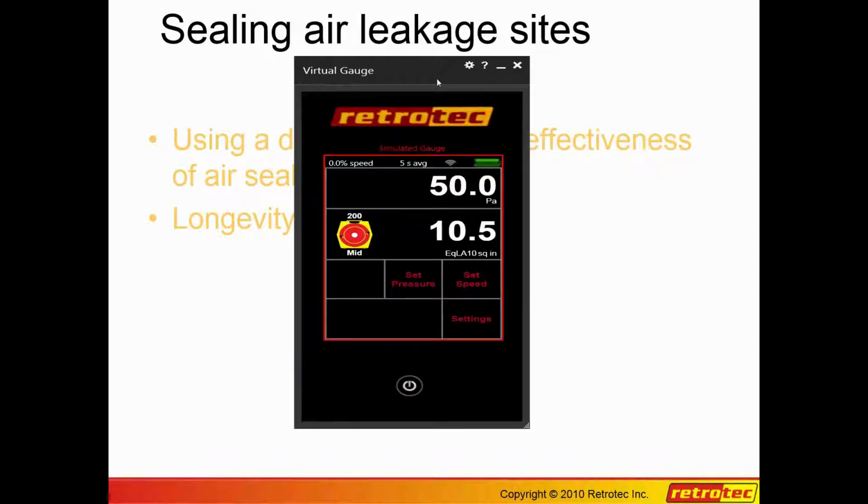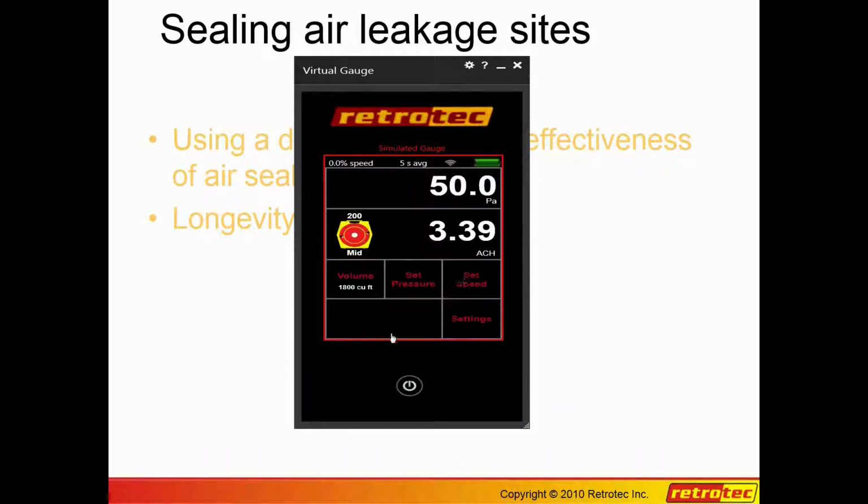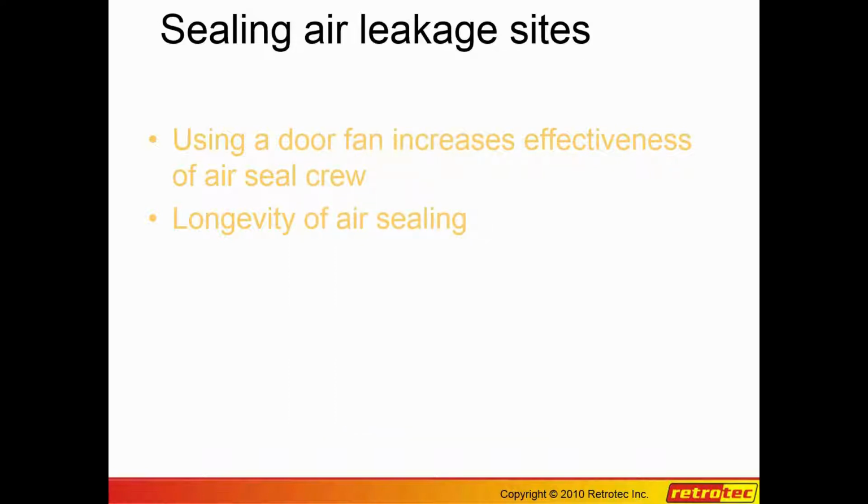And I suggest that when you're doing leak location that you do it in EqLA so that you know what size of hole you're looking for. You can easily just click on this and change it to air change rate anytime you like, and you can flick back and forth. Super easy.